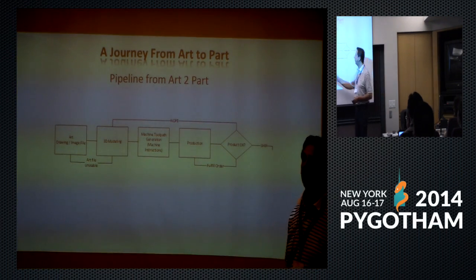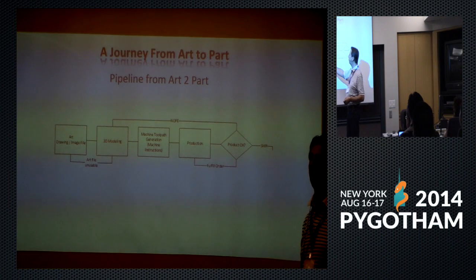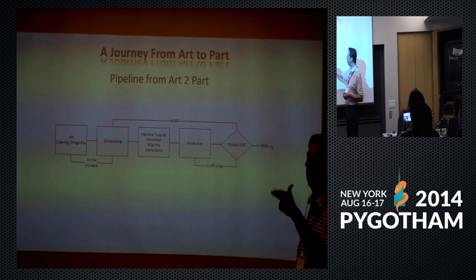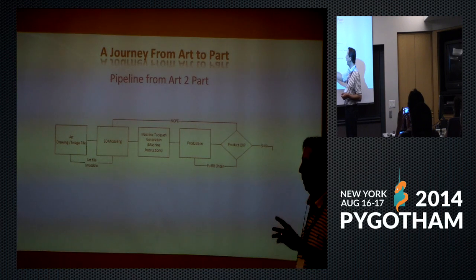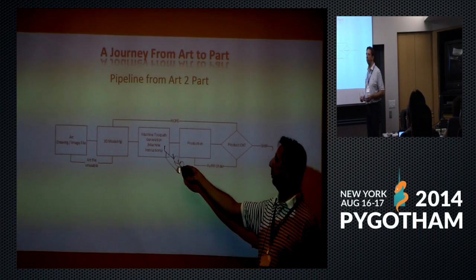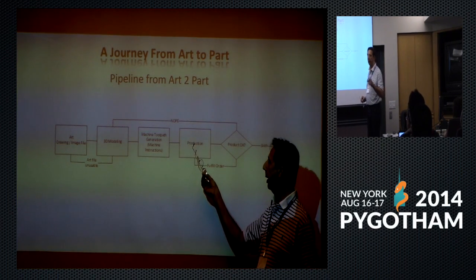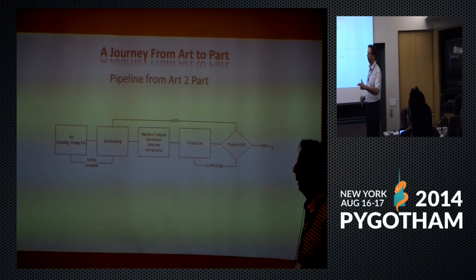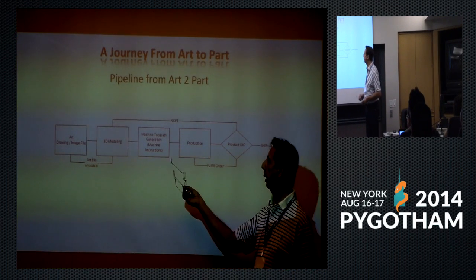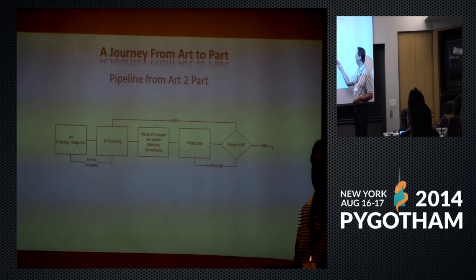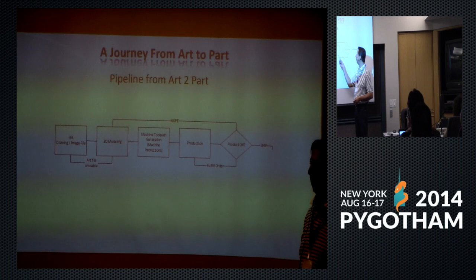Then there is a program which generates, and that's where we nail down which machine we are using, the machine toolpath. Toolpath is a descriptive word for where my cutter goes, or where my hot wire flies. This is determined there. After that, this code will be loaded into the machinery and then tried out.